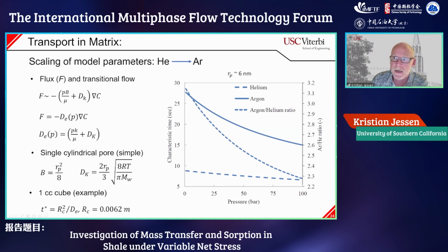The characteristic times include information about an effective diffusivity and a shape factor. So the way we approach this was to say, we're typically in some sort of transitional flow where we can have contribution from viscous or Knudsen type diffusivity. There are other models out there that try to cover a broader range in terms of mean free path, etc. But here we use the simplified idea just to get a sense of what happened, and then we'll take a